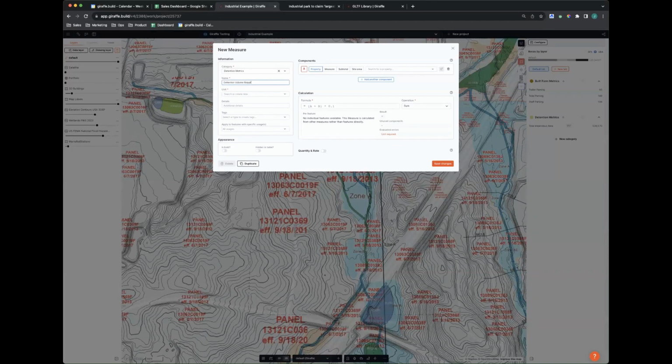volume required. And this is now in cubic feet, where we take that previous measure of total impervious area, A, and we multiply it by our coefficient, which is usually like 3/4 of an inch or something like that. So to get that into feet, we'd say 0.75 divided by 12. And there's our volume calc, 33,000 cubic feet of water.